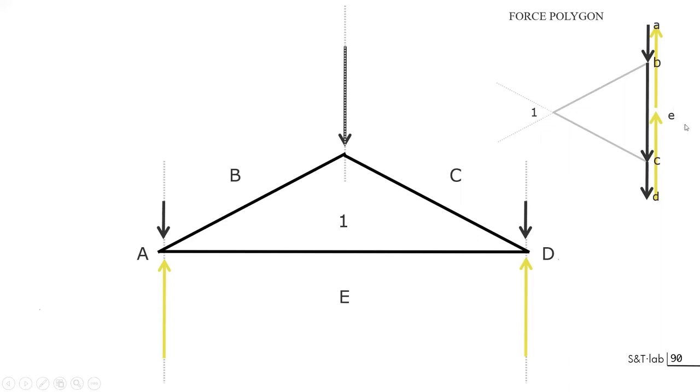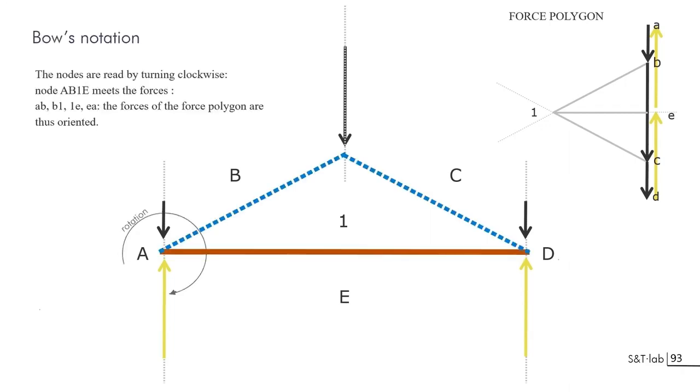And actually, the solution is not always met, but in this case, you can see that the orientation will be horizontal and passing through these 2 points. And that gives you the opportunity to check that the system is well solved and will be in equilibrium. And that's one of the main advantages of graphic statics.